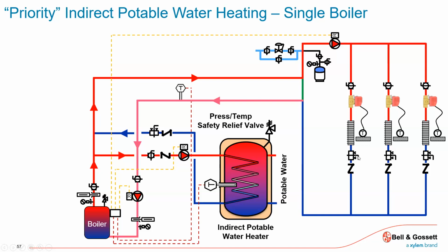Well, if I pipe the hot water supply to the indirect, and that indirect is very similar to that tank that's sitting right over there next to you guys on your left. It's a cutaway showing the coil inside, but the vessel has your potable water that's going out to your tub, shower, sinks, and then the boiler water goes through the coil to heat the water. So that's why they call it indirect. There's not a flame underneath it. The flame is sitting over here. So I'm kind of indirectly heating with boiler water.